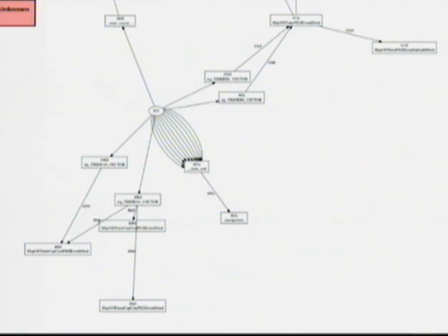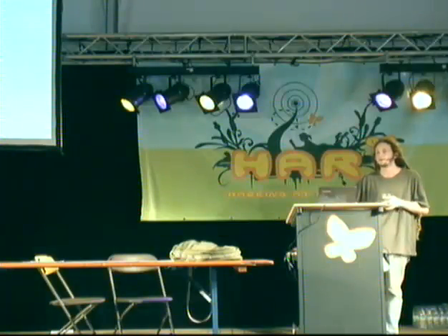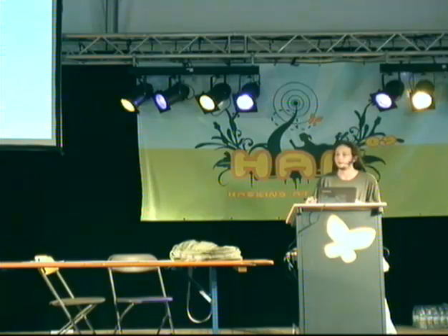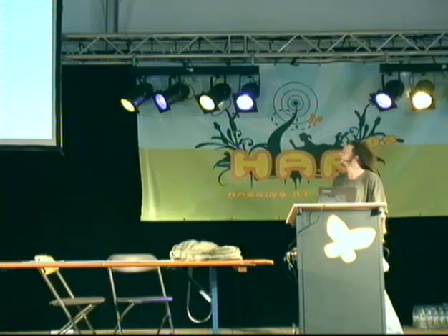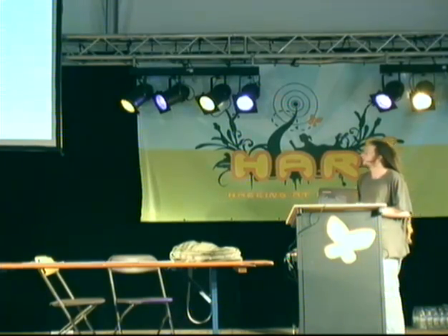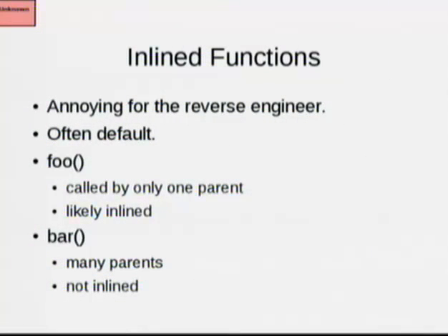And then you can see here that these interrupt handlers are all unused. So if you see many different interrupts going to the same target, it's probably an unused handler. All it's doing is making sure that the chip doesn't crash by some invalid address being pushed in by mistake. You also have to worry about function inlining, because on these platforms, having such little RAM and such little stack space, it's more efficient to inline a function and save that call on the stack, even if you have enough flash memory to hold it. Because the code executes from flash memory, it does not execute from RAM.